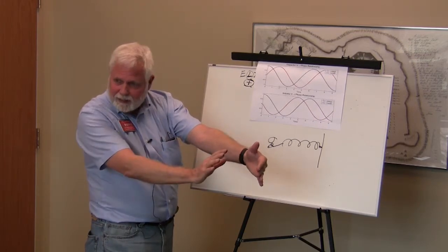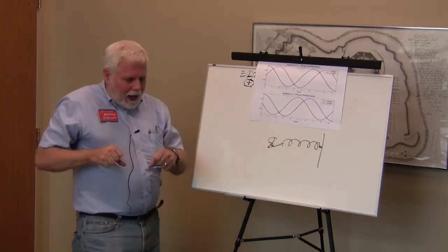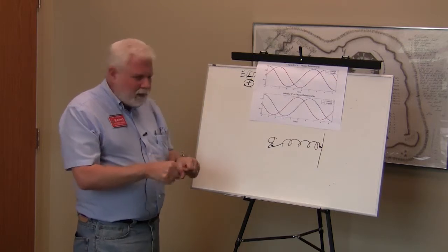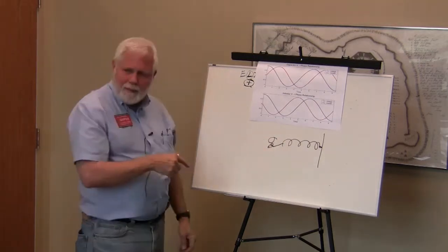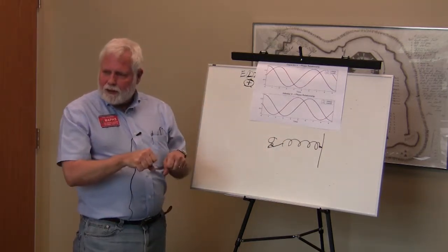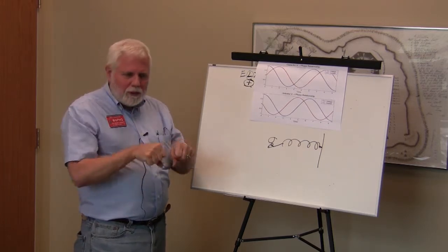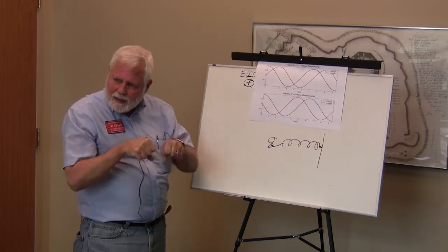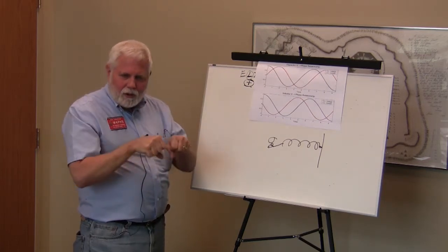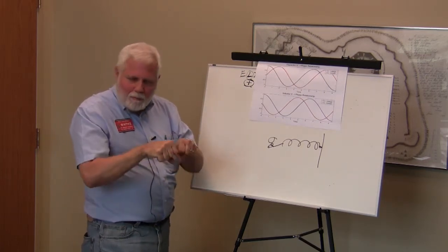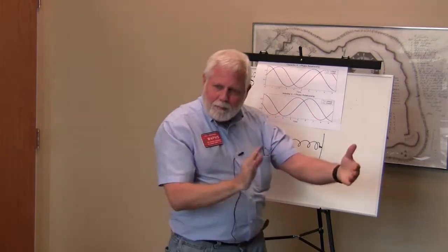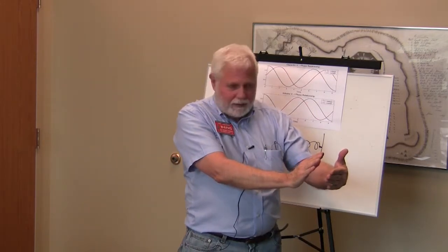The spring, got the idea? I start pressing against it. It starts moving. The speed starts moving immediately, but the force is still very low because the spring is not compressed. So which one leads here? The speed starts increasing immediately, but the force doesn't build up until I compress the spring down.